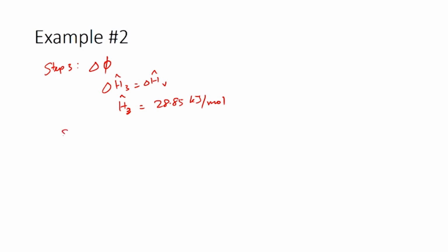Now step 4, which is delta T, where only temperature changes and phase and pressure are constant. H4 cap is integral Cp dT. However, here it would be the Cp of hexane vapor and temperature increases from 69 to 300 degree Celsius. You can get the Cp value from the tables or from some handbook.